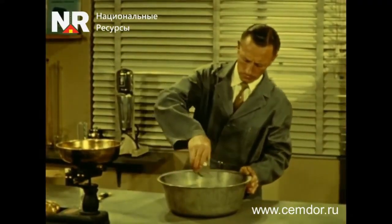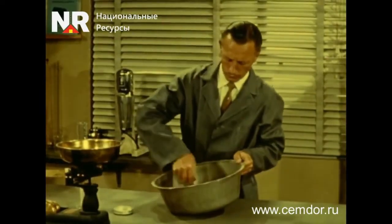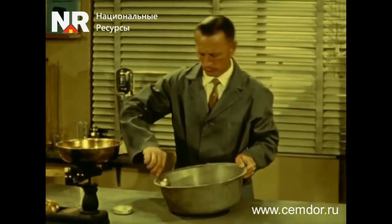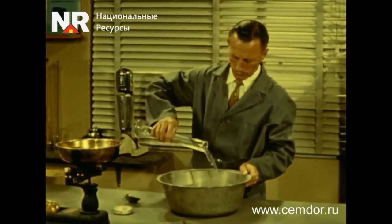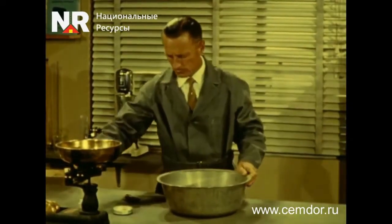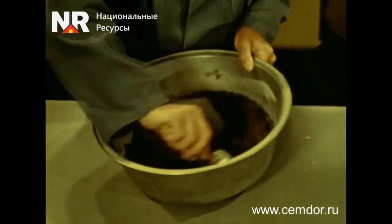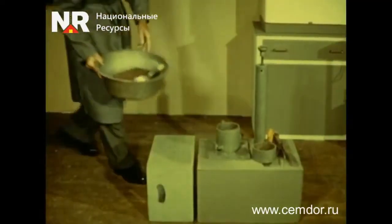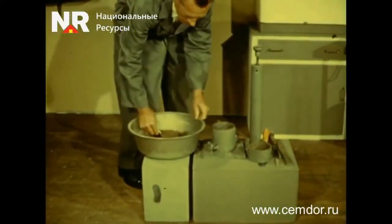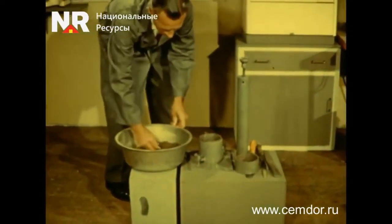Cement is added based on the required strength characteristics of the soil concrete. The amount of water needed to moisten the selected sample to the moisture content of the first test is calculated. The calculated amount of water is added to the selected soil sample in several steps, mixing the soil with a metal spatula. To determine the maximum density and optimal moisture content of the soil, the test sample is loaded into a special mold in layers and compacted.